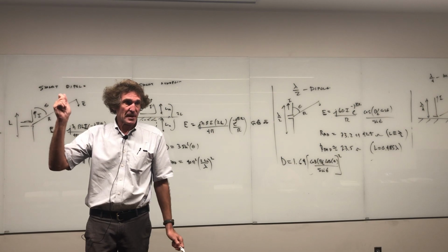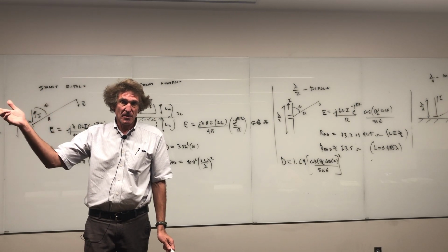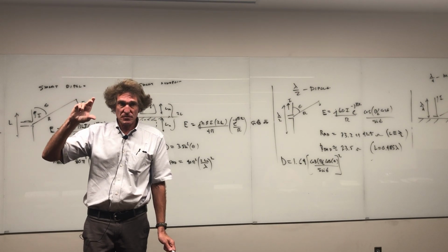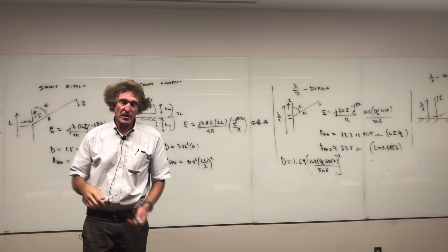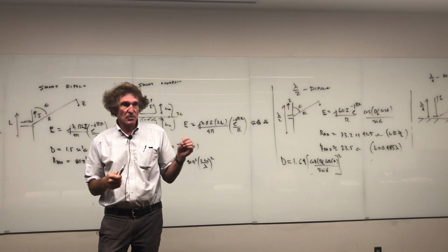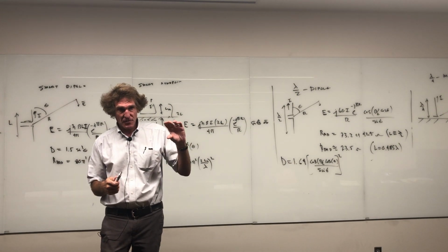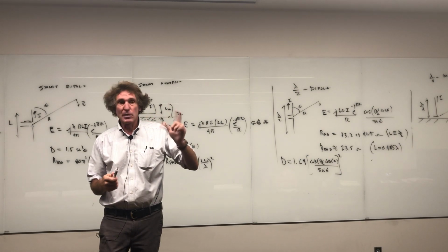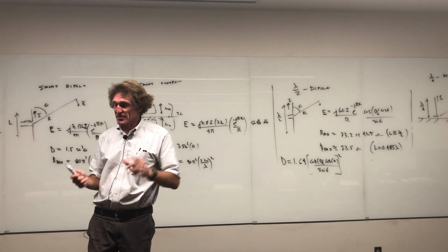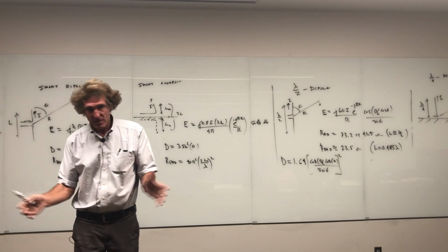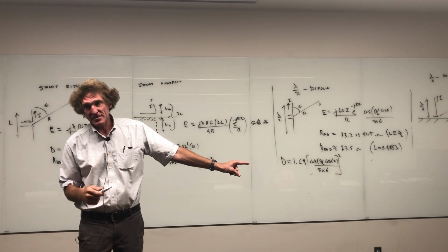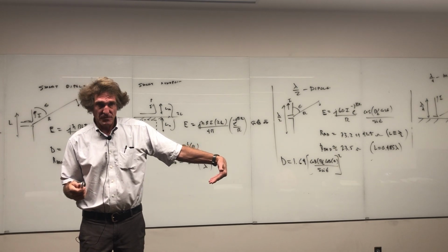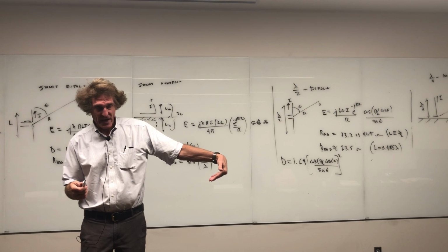They'll blow up. Do you know what electrolytics are? Those are polarized capacitors. They can store a lot more charge, a lot more energy, versus a normal dielectric, but they're polarized. And if you try to short those and send current the wrong way through them, they'll blow up. I've actually been over to the Space Power Center, and I remember years ago when we had a railgun project, they showed me what a blown up capacitor looks like, and it literally is a grenade. It may kill you if you're too near, so you don't want to ever have that.